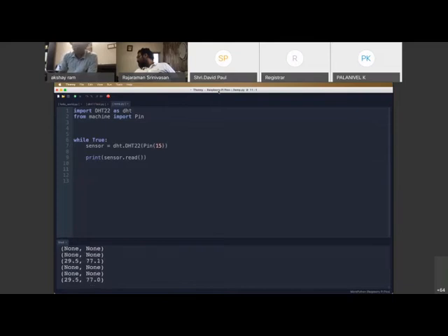So what had happened was I accidentally powered it from the 5 volts instead of the 3 volts. So I was looking up the drawing to make sure. If we can see over here, now we're printing the values continuously. What had happened was I had accidentally connected it to the 5 volt instead of the 3. So now I just checked the drawing once again and I replaced it.